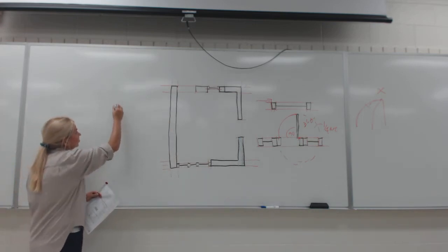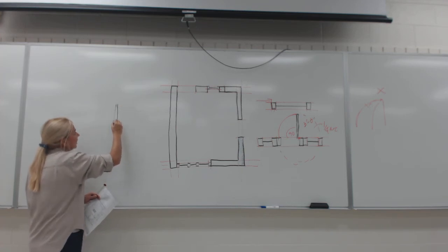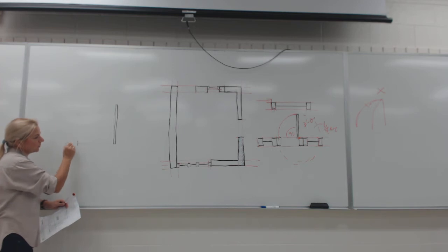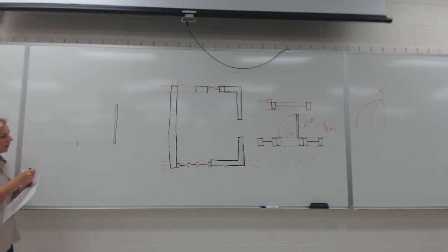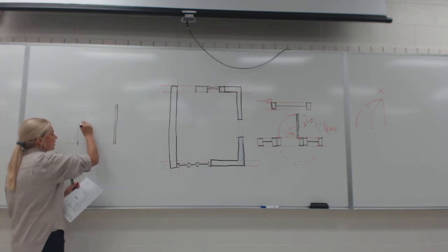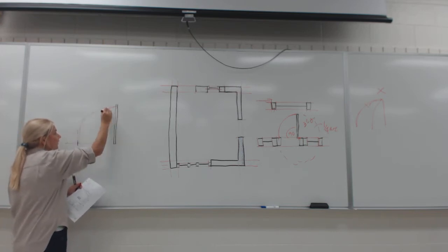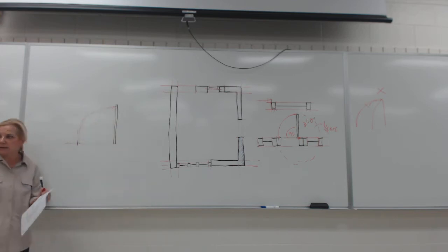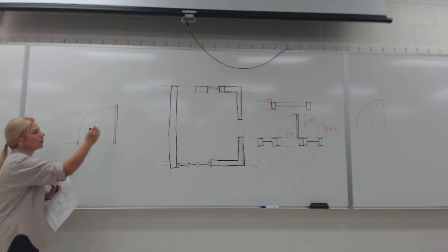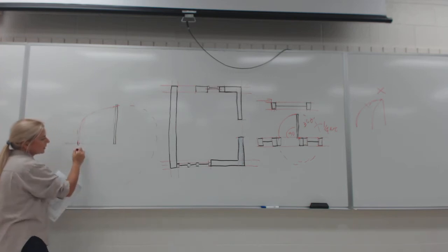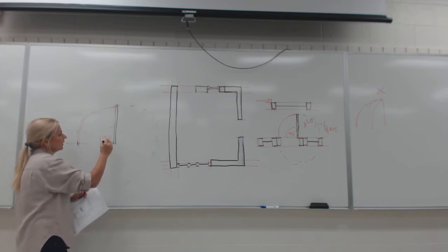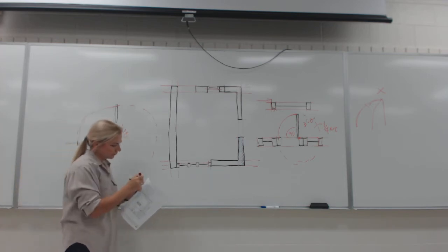If you draw your 3-foot slab, but you can't get the arc to get 100% to this point, then use the arc that's just, let's say you got the arc right here. Well, draw it as long as it's quarter arc. If it hits the door slightly lower, that's okay. What we don't want is an arc that's not quarter of the circle. So that's the main thing about the doors, okay? 90 degrees perfect and quarter arc.